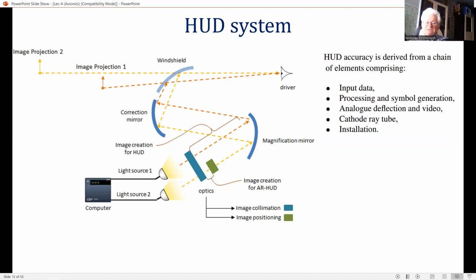The HUD is rigidly attached to the airframe and aligned to a fraction of a milliradian by mechanical and electronic means. The alignment of optics and CRT also benefits from the rigidity of the HUD chassis, such that the boresight error can be as low as 0.15 milliradian in pitch and yaw, and up to 0.6 milliradian in roll.